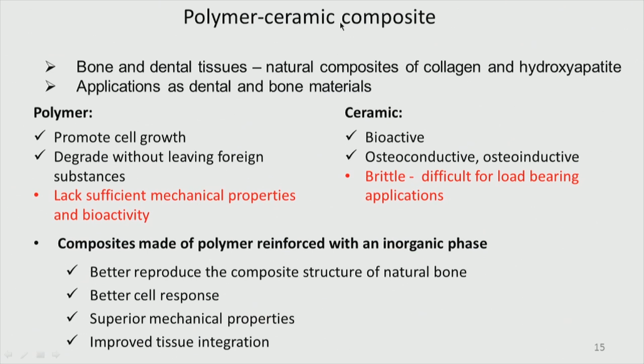So, polymer ceramic composites, for example, collagen hydroxyapatite. Collagen is a polymer, hydroxyapatite is an inorganic material. So, they add to each other and they give a lot of strength. They are used in dental and bone applications. Okay. Polymer will promote cell growth, the ceramic is bioactive. Polymer can degrade without leaving any foreign substance, whereas the ceramic is not going to be degrading. They may be helping in osteoconductive, osteoinductive properties. Okay.